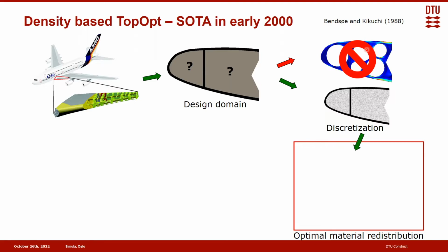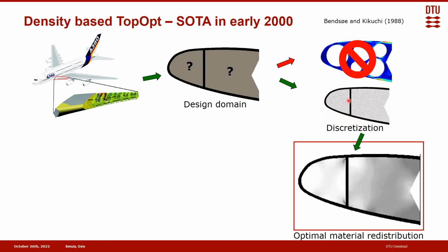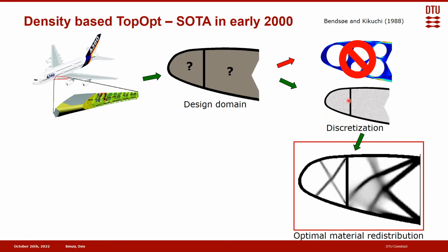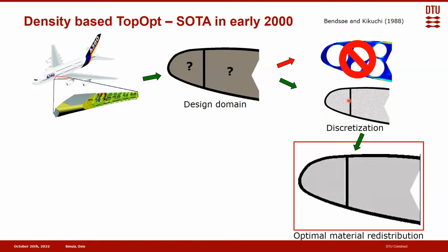Anyways, the idea with topology optimization is then that we just discretize our design domain, and then we do continuation, solve an iterative process, update the design field, with regularization included and everything, and we get to some nice design. And of course, as a mechanical engineer, no big surprise, there are no round holes. You simply do not see those.